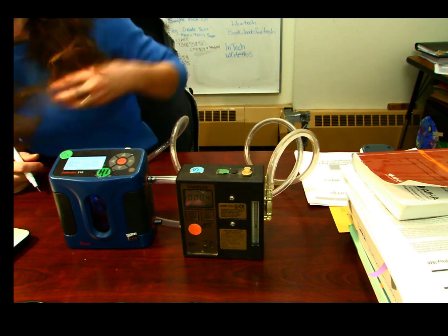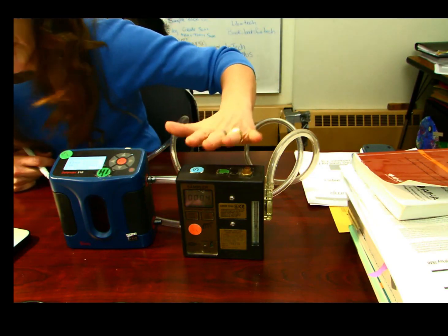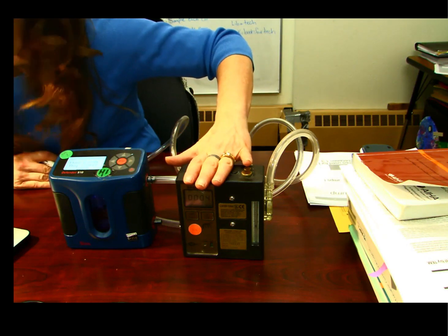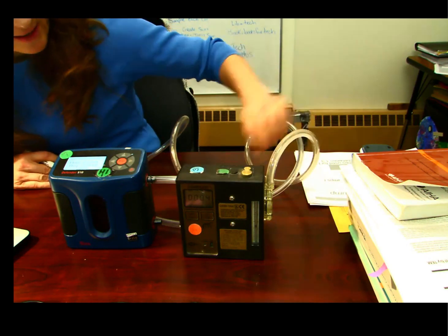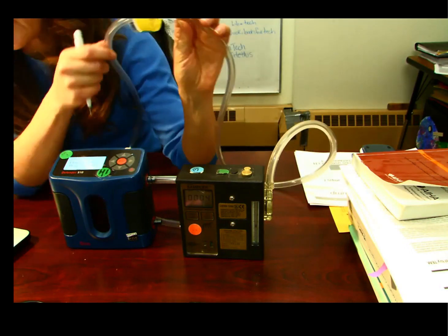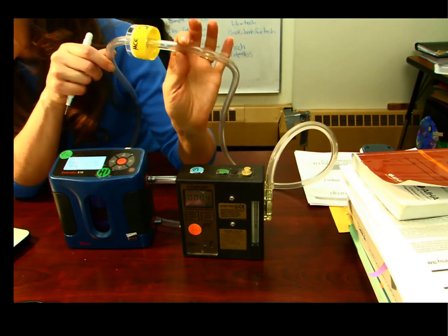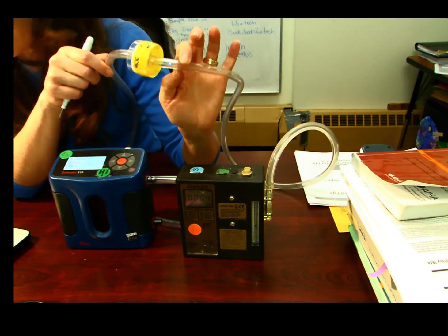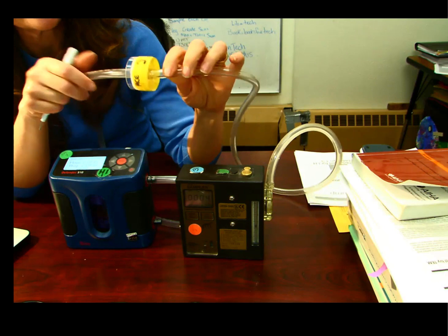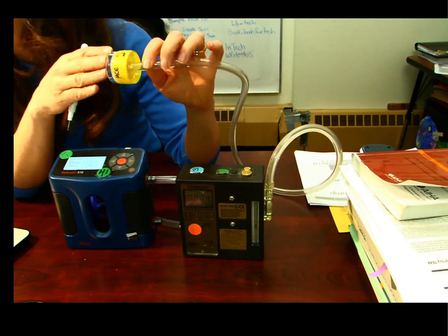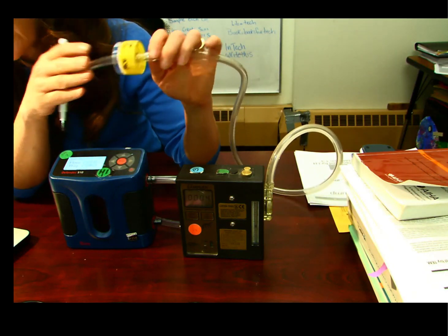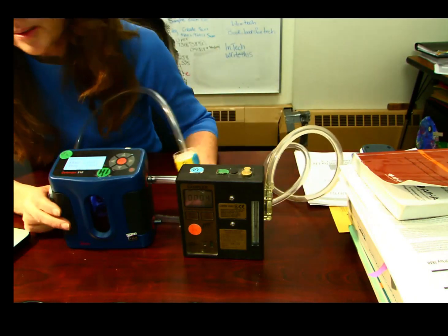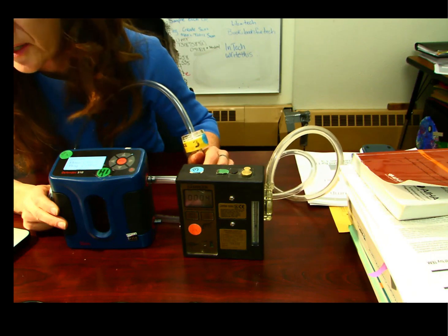Okay, so I have my sampling pump here. It's been running for 5 minutes and it's warmed up. Connected to the inlet, I have my sampling media. This is exactly like the sampling media that I'm going to sample with, although I've labeled it as a calibration media, so I'm only going to use it for calibration. Connected to the inlet, I have another tube, and now I'm connected to my primary standard.